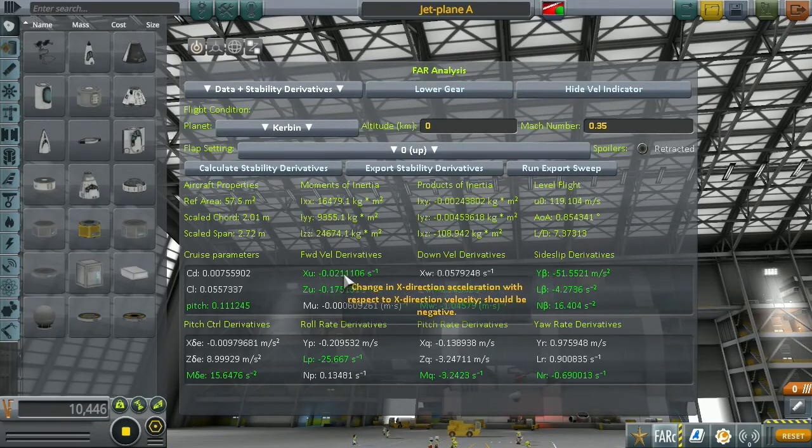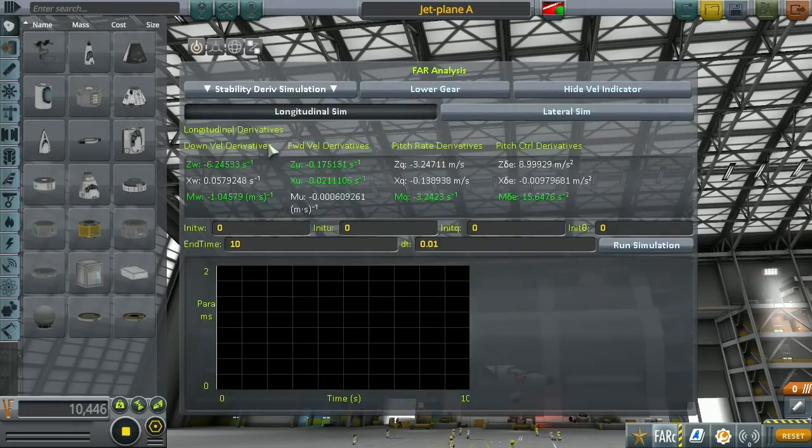It would start to decrease by this number, and conversely, if the speed was disturbed to all of a sudden fly slower than the equilibrium, the aircraft would start to accelerate back towards the equilibrium. Let us just remember this number for a moment. Basically 211% and a negative sign. That 211% and a negative sign is now this one.